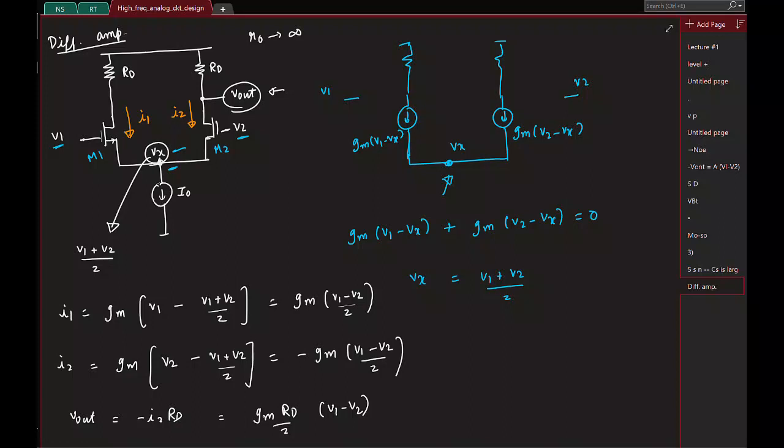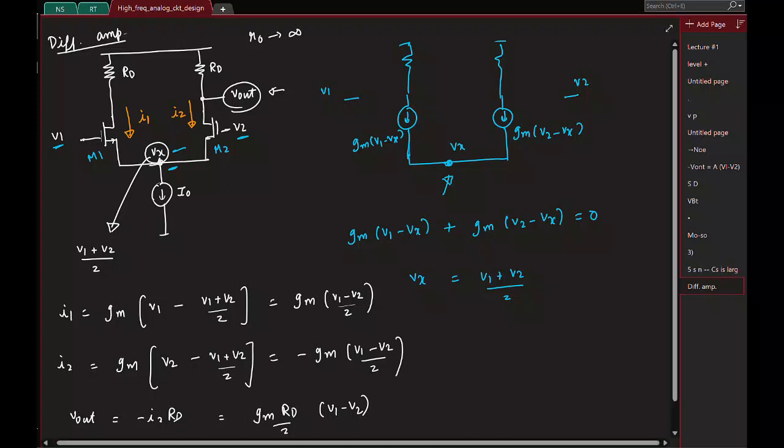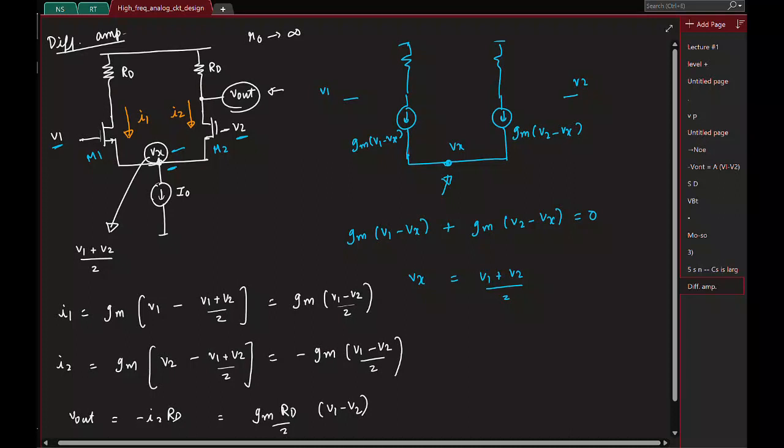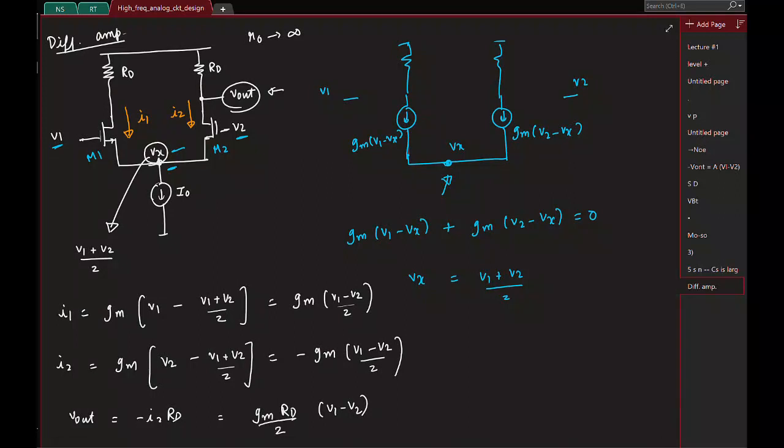Okay. So now you see that the gain has dropped down by a factor of 2 compared to having an ideal buffer. And that's simply happening because common drain or the source follower is not an ideal voltage buffer, and that's why we have it. Okay.